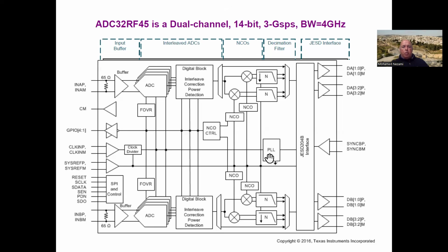There's a phase lock loop internally, and a clock reference that creates the CW in the digital domain that basically brings these samples to some frequency shift, presumably to baseband. And right after that, there's some kind of low pass filter.